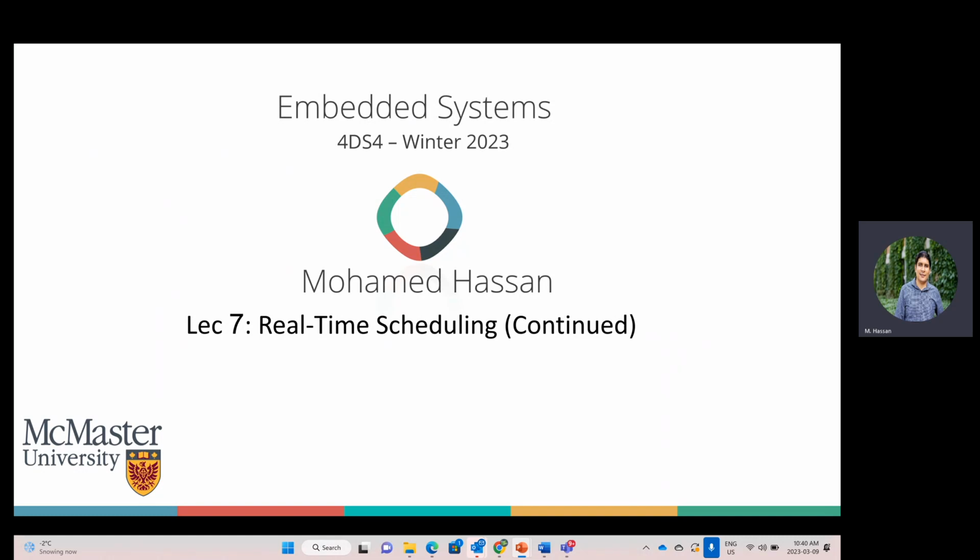The reason why we discussed real-time operating system scheduling, or if you remember why we even need an RTOS rather than a general purpose operating system like Linux, Windows or Android, is that we need strict timing guarantees. That's the main purpose why people use an RTOS in their systems and not something else. An RTOS is easier to analyze and more strict in terms of timing, which is why it should be used.